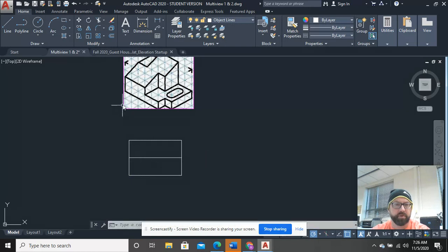Okay, so this is segmented off this portion of the box over here, which is 3 wide. So I'm going to go ahead and offset 3 in this case. Okay, and now I'm going to go ahead and get rid of what I don't need. I don't need this portion right here, and I don't seem to need this portion right here.